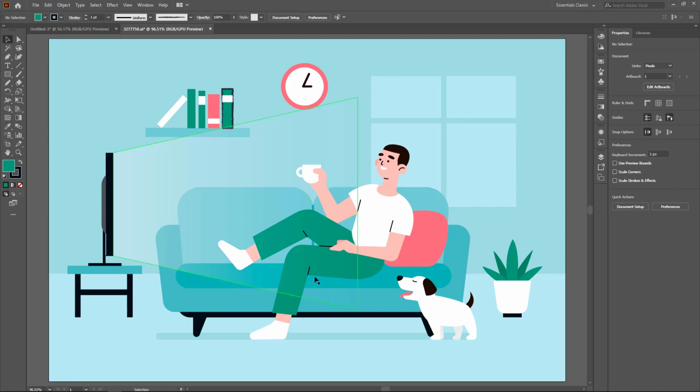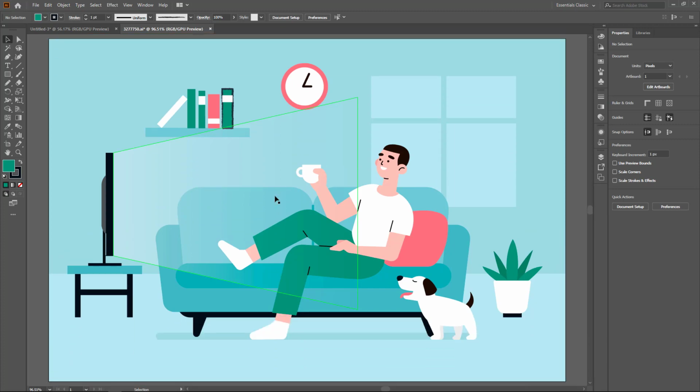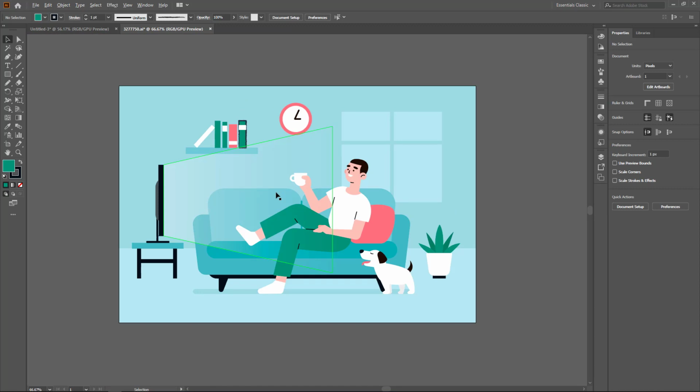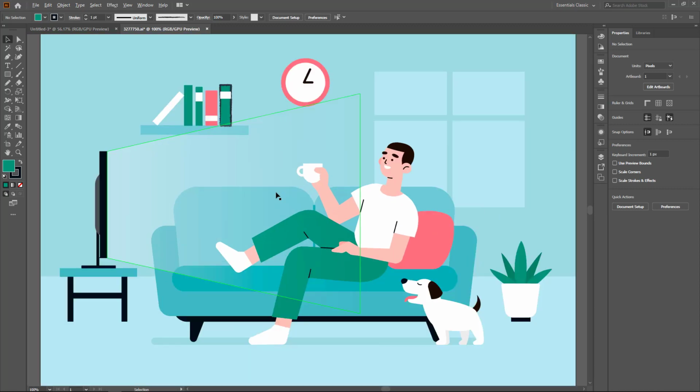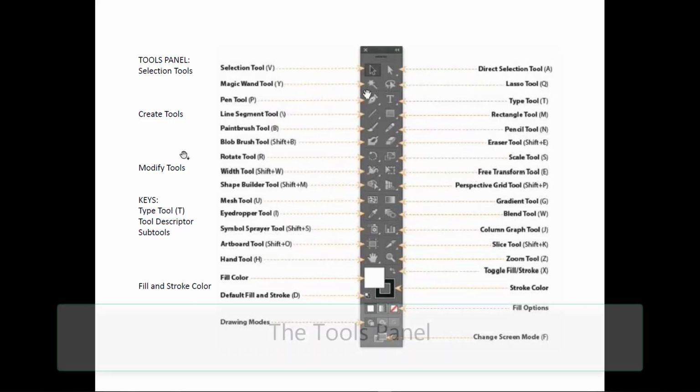Finally, zooming in and out is pretty easy, but it is slightly different than some of our architectural software. If you scroll up and down, you move up and down. So you can hold down Alt, which you can't see me doing because you can't see my keyboard, but in combination with the scroll wheel that allows you to zoom. You can also do Control plus or Control minus.